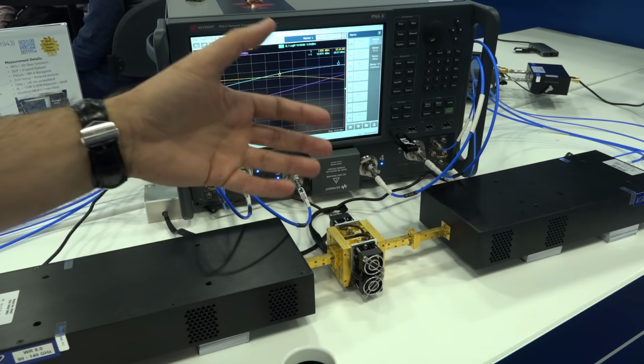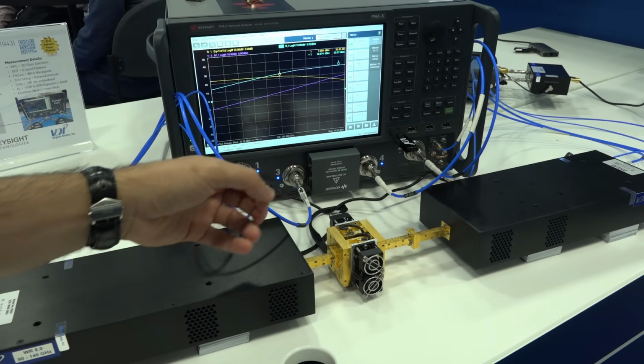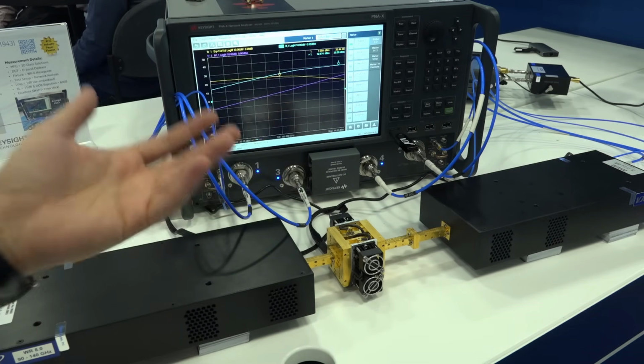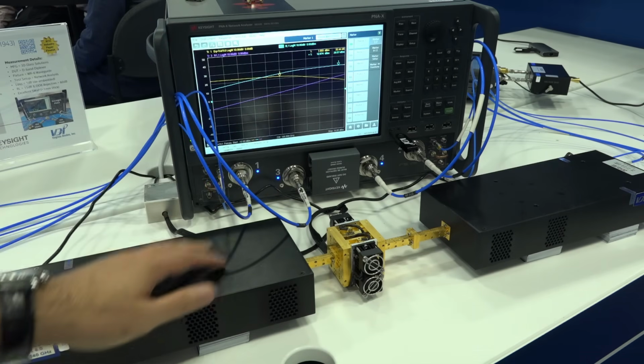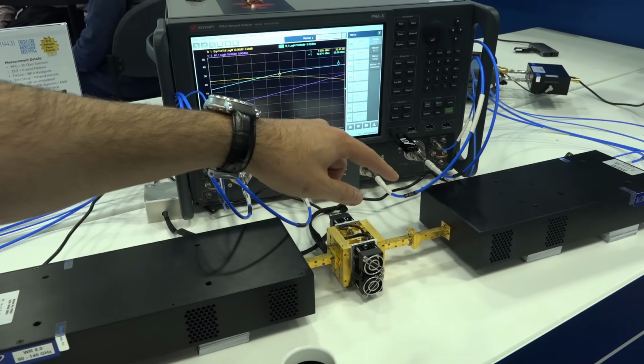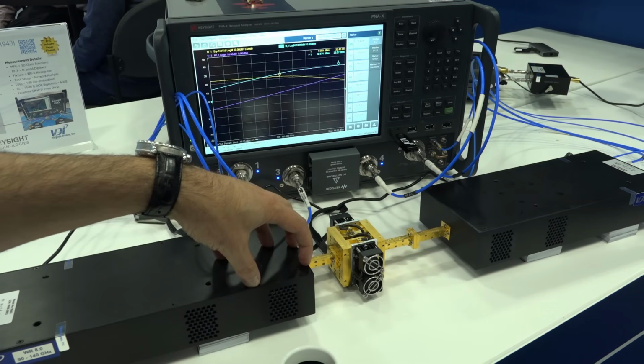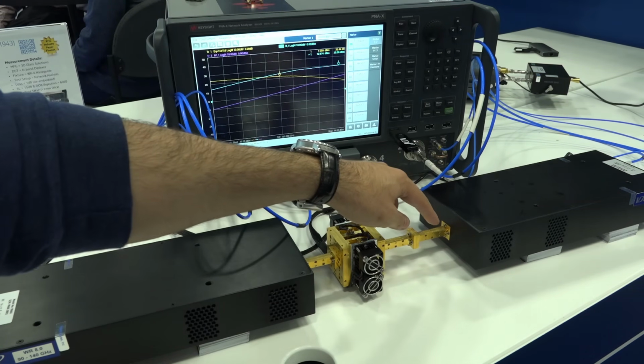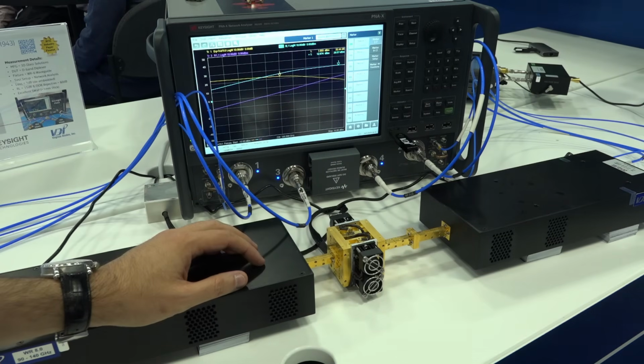You can imagine if you're doing things like load pull, or if you have amplifiers that need a lot of input power to compress them, how would you get that without having 30 dBm at the test port? Now on the other side, remember that if you're generating 30 dBm here, you have to be able to accept 30 dBm in the other side, because otherwise you won't be able to calibrate with a through.